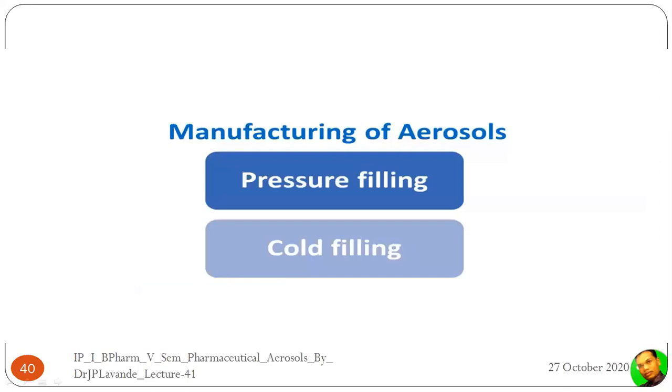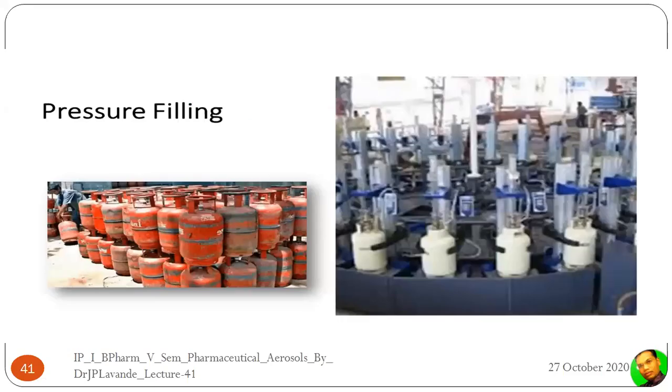As far as the manufacturing of aerosols is concerned, there are two different methods, pressure filling and cold filling. The pressure filling method is the same as the filling of liquefied gas containers, LPG cylinders, right?